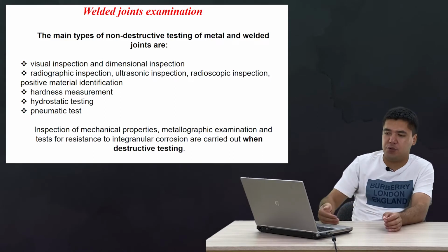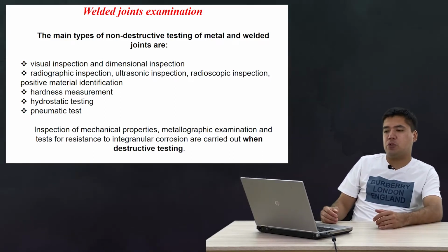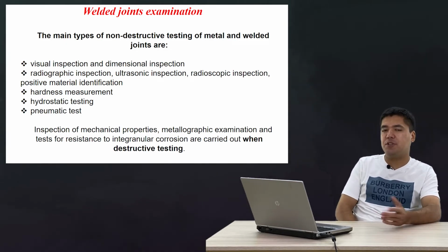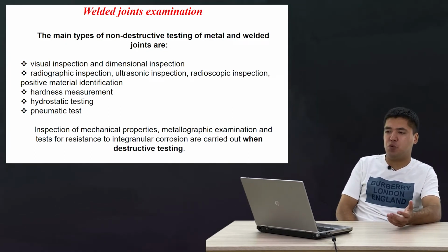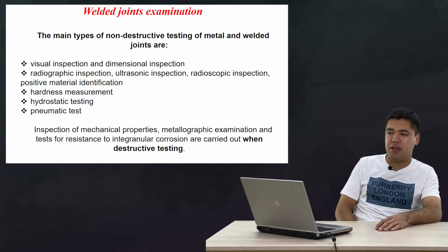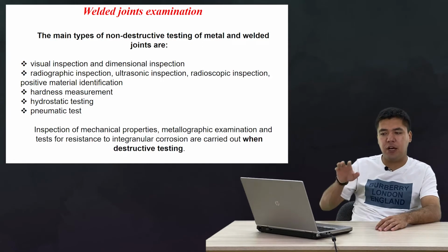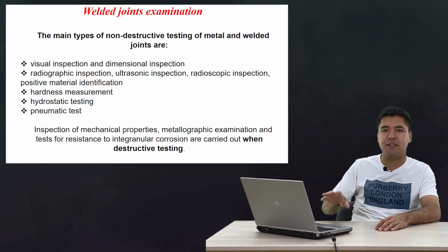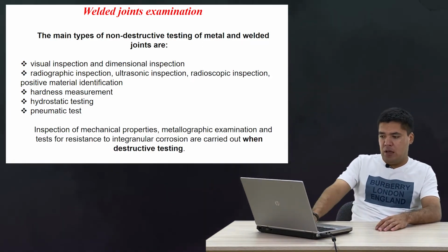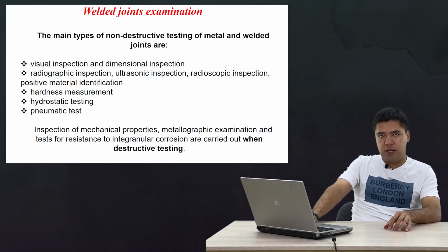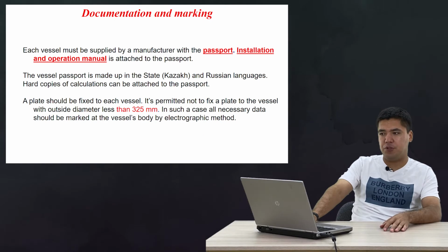And here during this training, we are going to pay attention mostly to the non-destructive test. And what is non-destructive test? It can be any test which is included in the list as shown in this slide, like visual inspection, hardness measurement, hydrostatic testing, pneumatic testing, and etc. And all test results shall be written in the protocol, and after passing the test result or quality test, equipment can be put into operation.